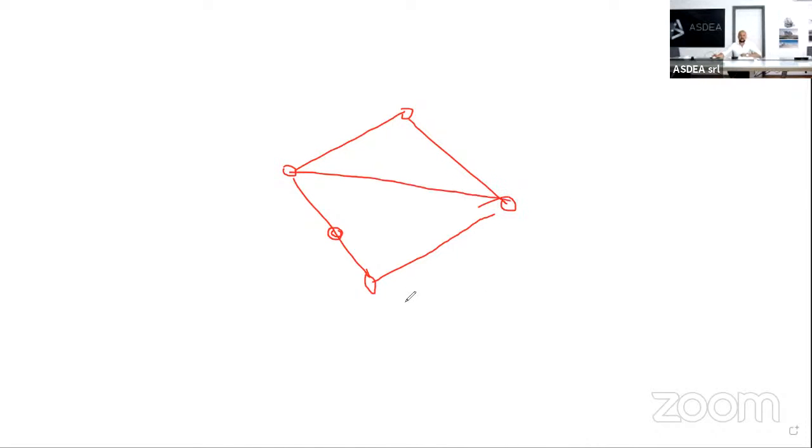Okay, so imagine that if you have a quadrilateral, for example, and I have a node here, well, in this case, using the full quadrilateral or the triangular subset does not change, because since I don't have any dependence on these two nodes, I only depend on these two, the displacement between them will be linear, and it is the same.